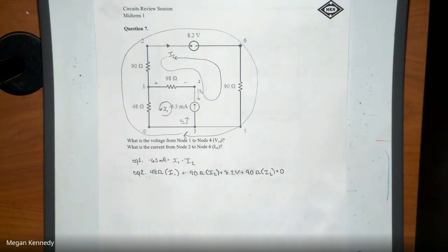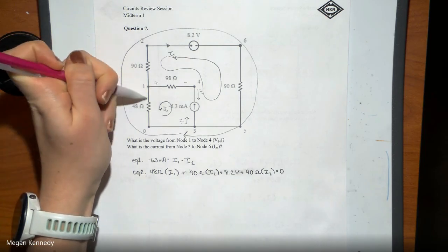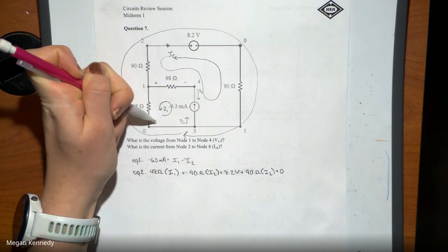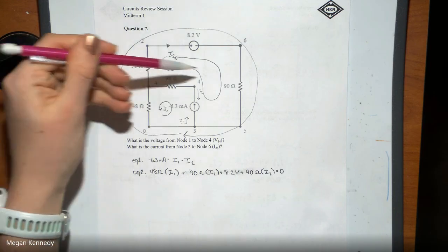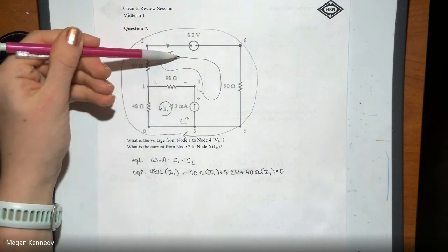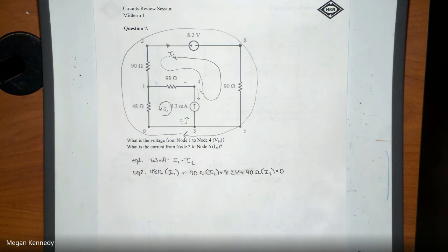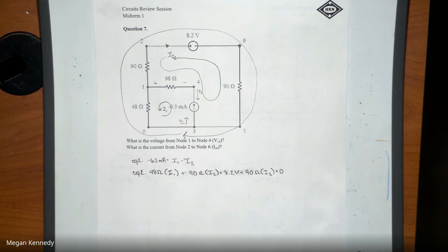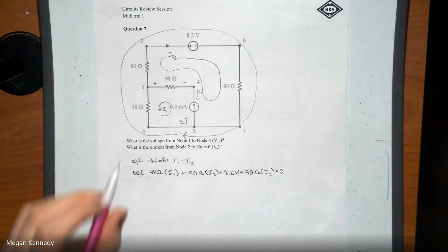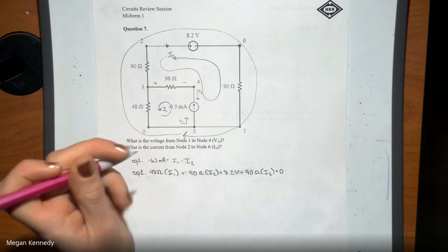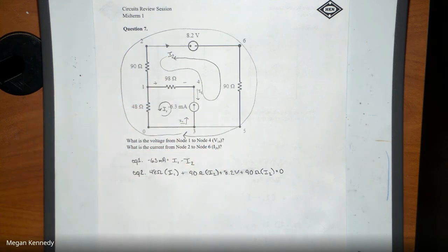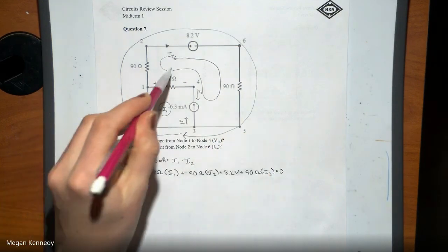Does that make sense how I went around the whole circuit and just followed the currents and the paths that they took? For this one, it's only getting touched by I1, so we only have to worry about I1, whereas these two are only being touched by the I2 circuit, so we have to worry about those. Actually, with how I have this defined, it would be a negative I2.